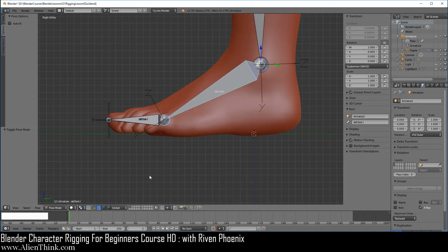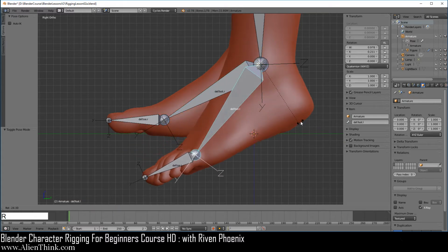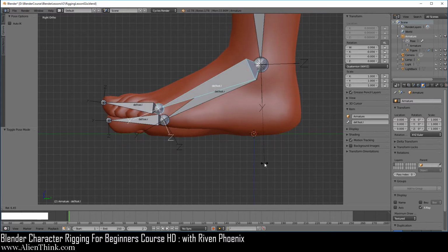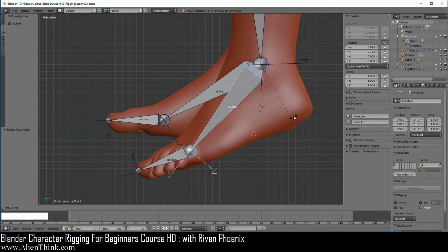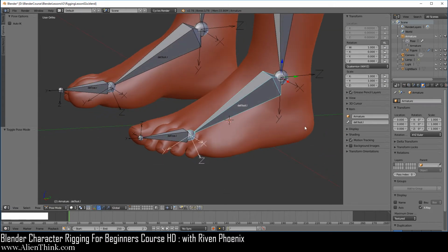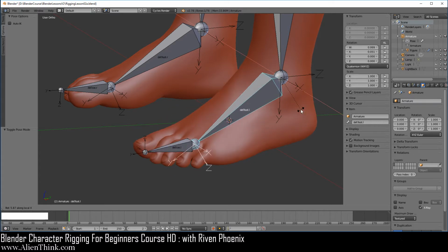Right click to cancel. So here we're just going to switch to edit mode and type in a 0 over here. And now the Z is pointing down. So here we'll just switch to pose mode, press the R key, now the Z points down and minor is its opposite. Right, and of course we know that it's rotating on its head around the x-axis because of the way the bone is aligned. So it's not like we have to press the R key, press the X key 2 times to ensure that it works. Right, it's just logic. We know that it's going to work.